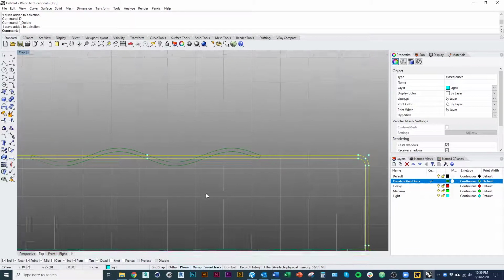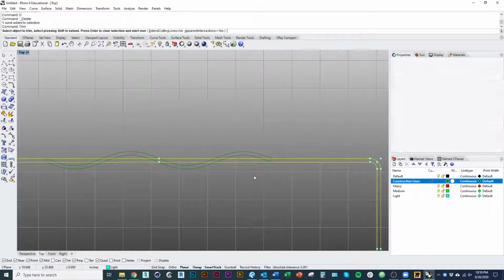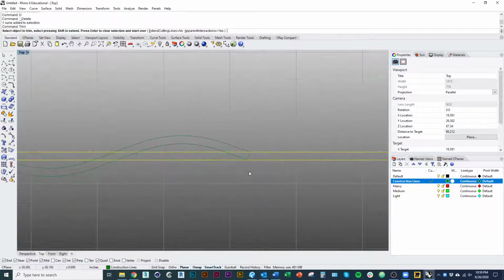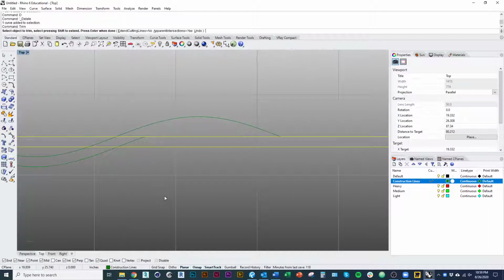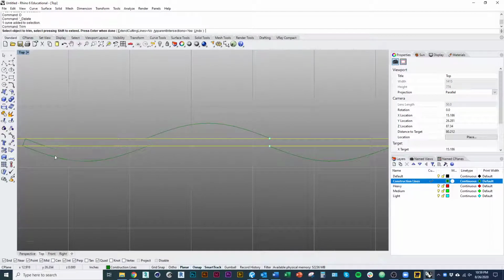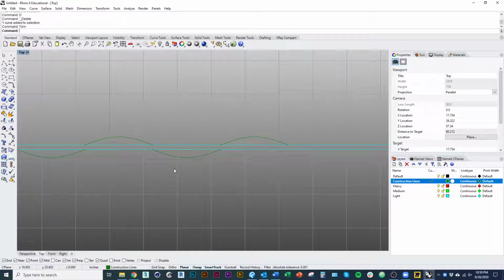So I'm going to take this original handle line that I've drawn, and I'm going to type in the command trim. Because I already had that line selected, that's the line I'm using to trim the other object. So if I wanted to trim away this stuff, because this line is in the way, I can click on that end, and it trims away whichever side I click on. Same is true there, and there, and there, and there. So I can trim away all the lines that I don't need. That's what you would see there.